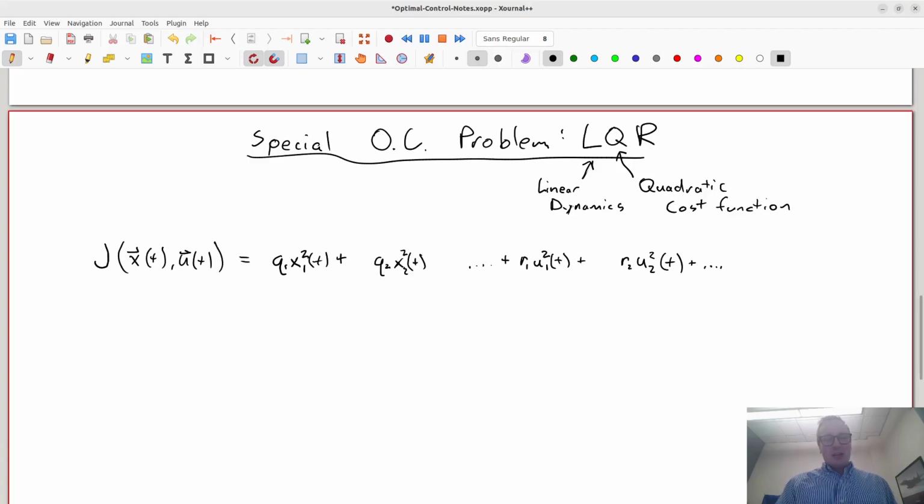Okay, if I just use this objective function, we have another problem, which is that this is only evaluated at one instant of time, at one t. What we really want to do is drive the integral of these state deviations from 0, over t equals 0 to infinity, to 0. So this is a way to represent the LQR cost function. This is not the most general version of LQR, but this is good enough for today.